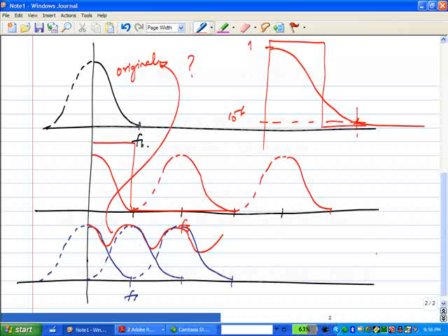Now the second part is statistical. That is a different thing. That is because, like every time I'm speaking, I'm not producing exactly the same sounds. Even if I say the same sentence, some things will be different. So the spectral density and so on is some kind of an average of my speech, like many samples of my speech, over and over. So that statistical thing you need to get, because first of all you have different things every time. Okay. I mean, that's the nature of information. If I was going to say the same thing now and the next sentence is the same thing, there is no motivation for you to sit here, right? So it's only because I'm saying different things. Now to describe it in the frequency domain, I'll need some statistics. Okay. But yeah, in practice you identify some point beyond which the energy is very small.